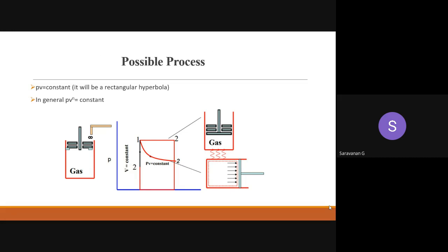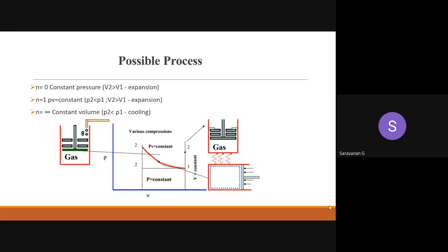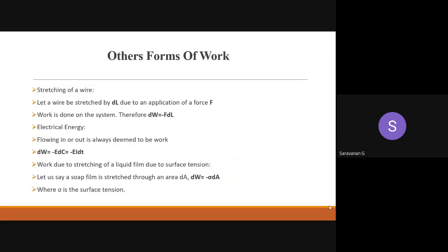See the diagram, how the volume changes occur. The gas fills the cylinder, and a load is applied to pressurize it. The piston movement causes a change in volume, thereby giving work done. One is compression, one is expansion, another is the constant pressure process, another is PV equal to constant, and another is PV^n equal to constant. These are the general work done cases.